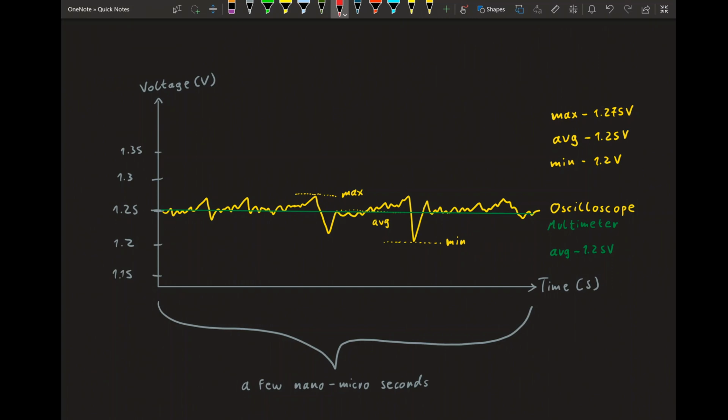No, there isn't anything broken. The cheaper motherboard simply has a worse performing VRM. That is not as good at transient response, that's just generally worse at voltage regulation and has worse voltage delivery. But our multimeter and HWiNFO, they can't tell us that. They will show us we have 1.25 volts and we know we need 1.25 volts, so why is it not working? Well, that's coming back to the time scale.